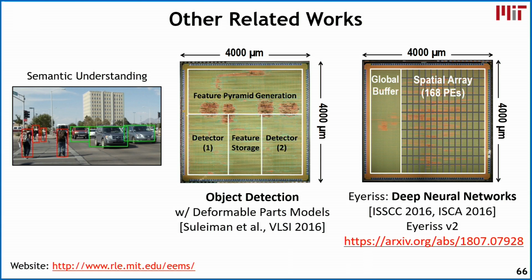One in particular is an object detection chip that we published in 2015, and in this particular chip, we're able to do object detection with energy that's less than video compression. The reason why we compare it to video compression is that that's a typical default, that you would compress the video and send it up. But for that same energy, below 1 nanojoule per pixel, we're able to do object detection at HD 30 frames per second.